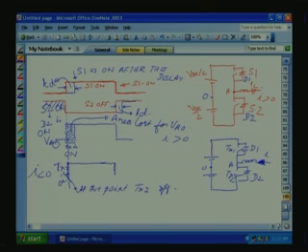Transistor is off, but current cannot change instantaneously. So, diode will immediately conduct. So, from here to here, D1 will be conducting. At this point, what we will do? Transistor 1 is off. Okay. But since D1 is conducting, the transistor turn on or turn off will not have effect. So, D1 will continue to conduct till this TD period.